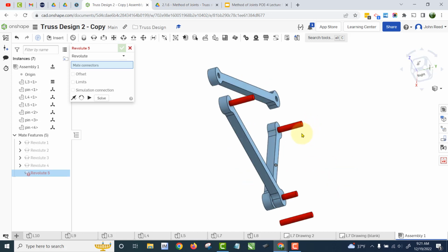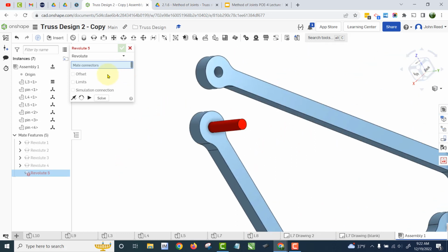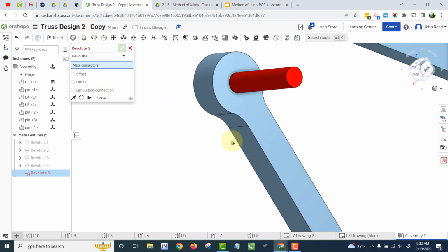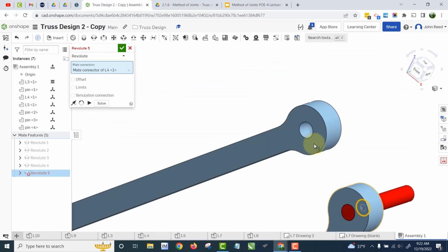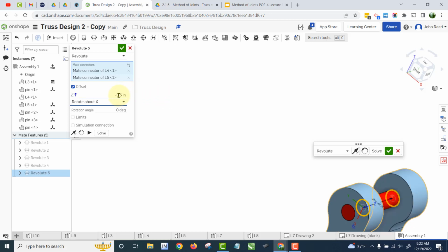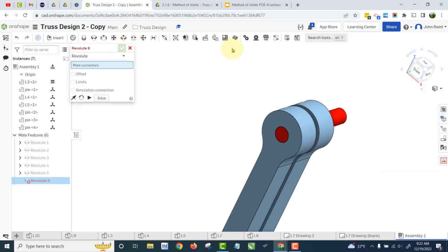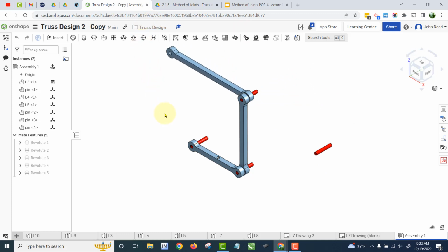That's good. All right, now let's turn to this side and put a revolute mate right there. And just because it's oriented this way, I'm going to turn it. I don't think I need to. And remember, I have to put an offset of minus 0.05. And I'm going to accept that. Shift 7. And this guy should be able to just swing around like so, all the way around, and hopefully meet up right there.